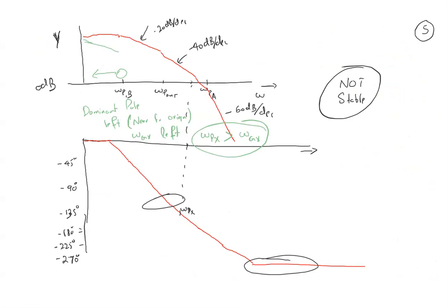Yeah. So I can have something like this. It's crossing the unity gain bandwidth frequency now. Earlier, if my system was not stable, now the system is stable. So that's the benefit we can get with the help of frequency compensation. Frequency compensation helps a lot in achieving these things.